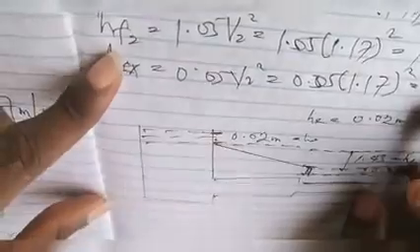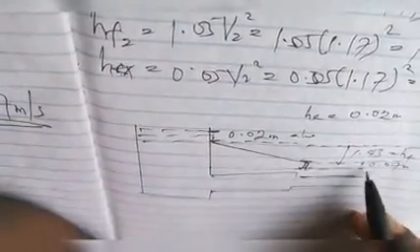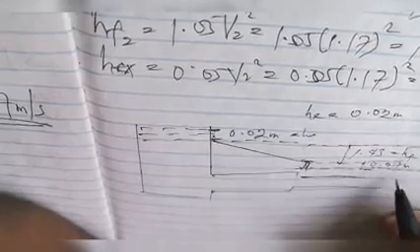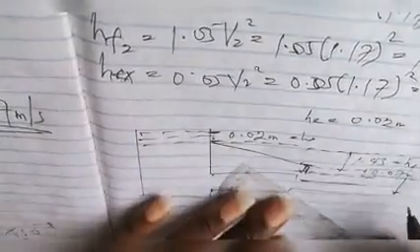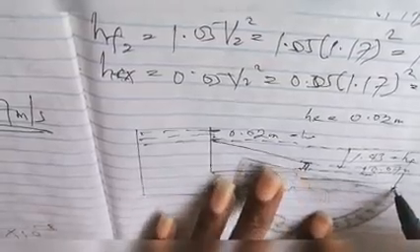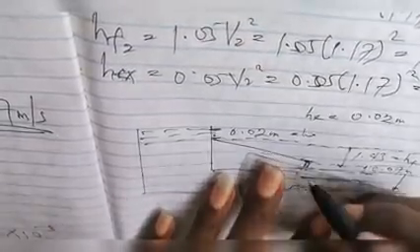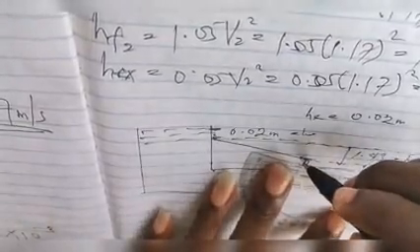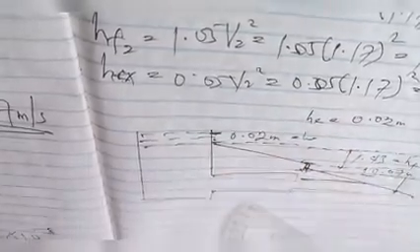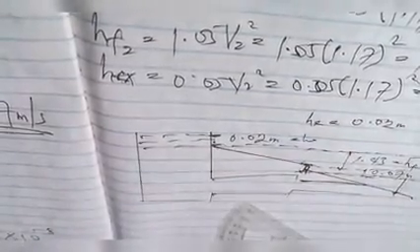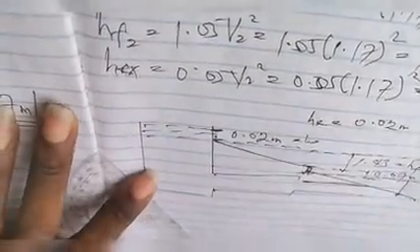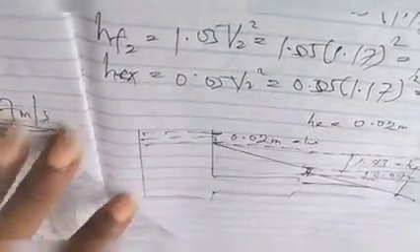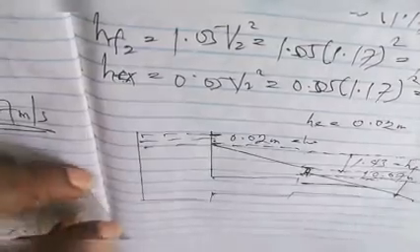Finally, or second to last, you have head loss due to friction in pipe 2, which is 1.38. So from here now, from this line, you measure 1.38. 1.38 should be somewhere down around there. So you join these 2 points, head loss due to friction in pipe 2 and the contraction, together. I think I should have used a red pen for this. So you have this line.